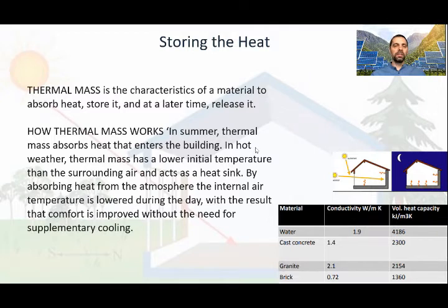In the winter, when the sun is allowed to shine on them, they can be charged up to help warm the house by transferring the sun's heat inside. And when the surrounding outside air temperature drops, as the air cools after the sun has gone down, the thermal mass will continue to release its stored heat energy. When all the heat is discharged, it is ready to once again charge up or absorb heat again. Thermal mass is measured in terms of volumetric heat capacity. Thermal mass properties of some materials are presented in a table below.